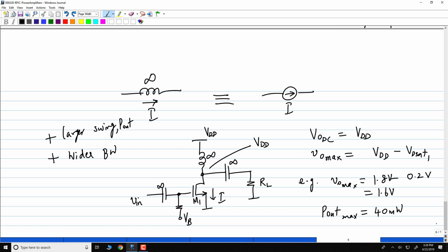When the bias current and the incremental current become equal, or you can alternatively put a condition at the gate saying that the absolute input voltage at the gate of M1 falls below VT. Either of these two conditions is allowed. They are almost the same but not exactly the same, because of the square law of the device. But for all practical purposes, you choose one and calculate it. When we do the calculations, we will discuss that.